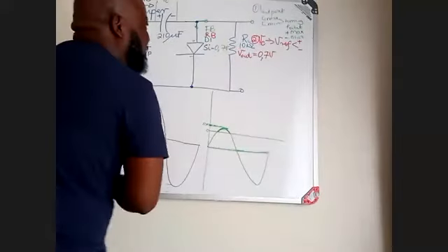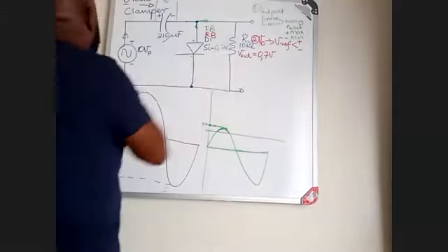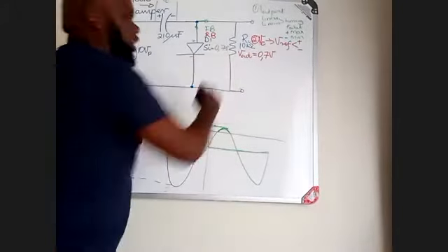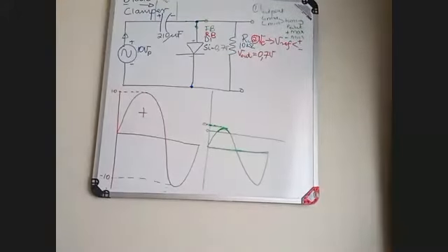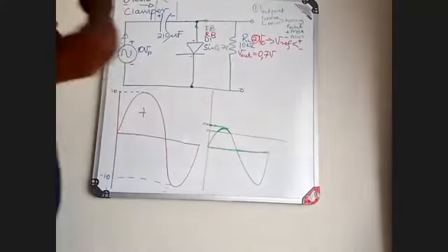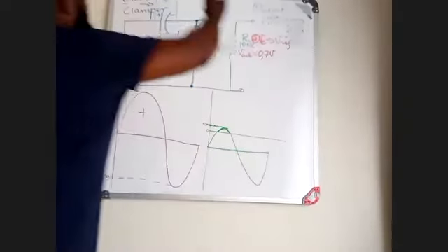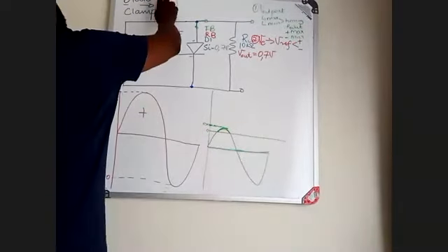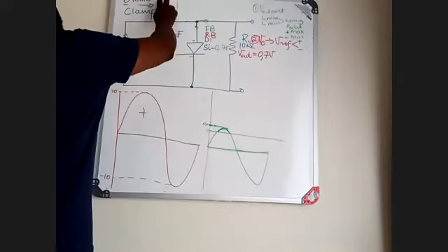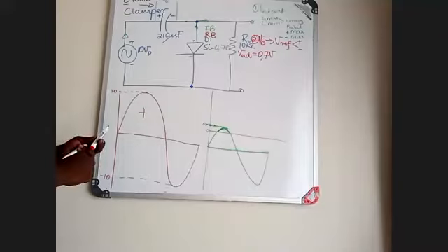When your signal shifted, its maximum is no longer 10, but becomes 0.7 volt. If the maximum becomes 0.7 volt, your point of reference also changed. The new point of reference is determined by how much voltage is established within that component there.